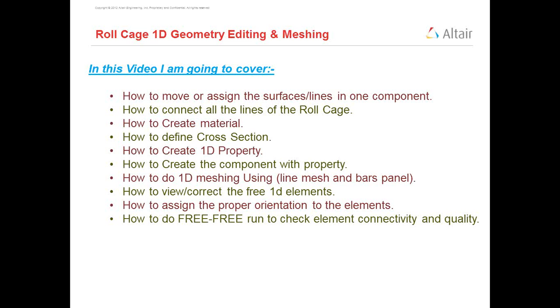If the shape of the element is not proper as per the interpolation function, the interpolated results will not be accurate, so there will be a big difference. That is why it is very important to have the element quality and connectivity checks.